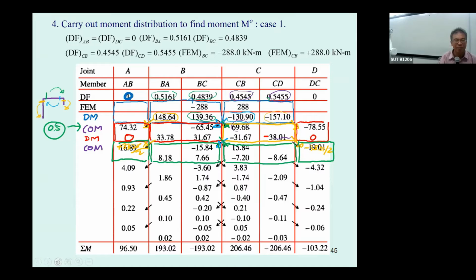Okay, again, let me tell you again. We have the frame like this. Our frame is subjected to 37.5 kilonewton meter, and now our frame is going to sidesway in this direction, and then you are going to determine the resistance force R. This resistance R is going to be resisted by the force A sub x here and the force D sub x here.